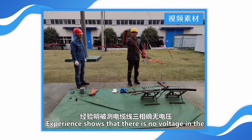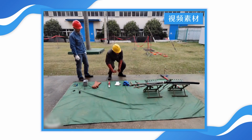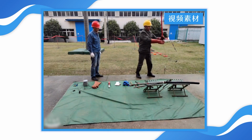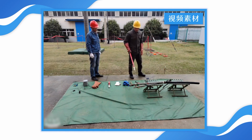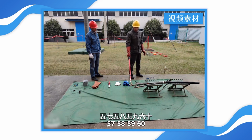The test shows there is no voltage in the three phases of the tested cable. Discharge the tested cable for 1 minute. 57, 58, 59, 60.